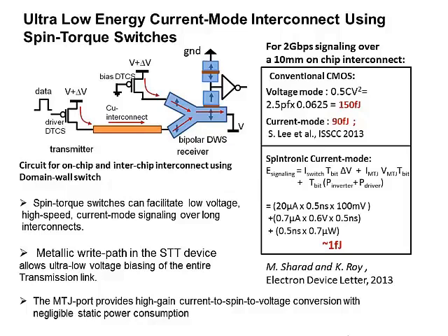So we see that this spin torque based device can be used to build very low power current mode data buses as well as very low power sense amplifiers, which are used to access the MRAM. So the two major power components in the MRAM technology, namely the sensing power and the data bus power, can be drastically reduced by application of these emerging current mode sensors.